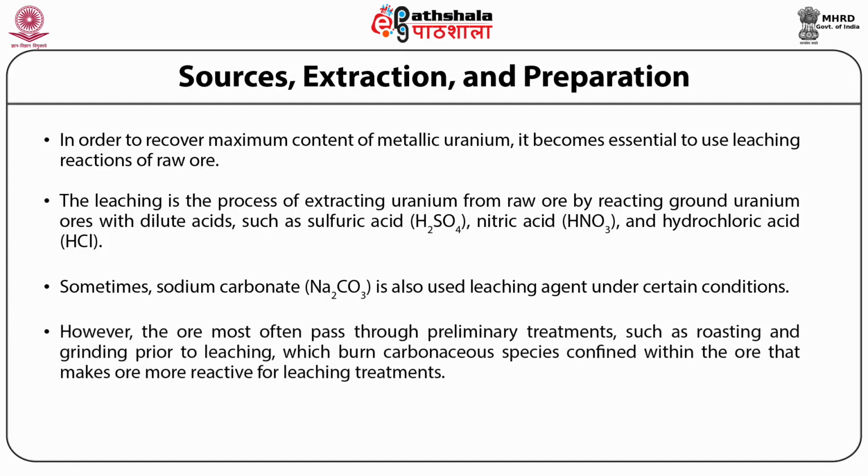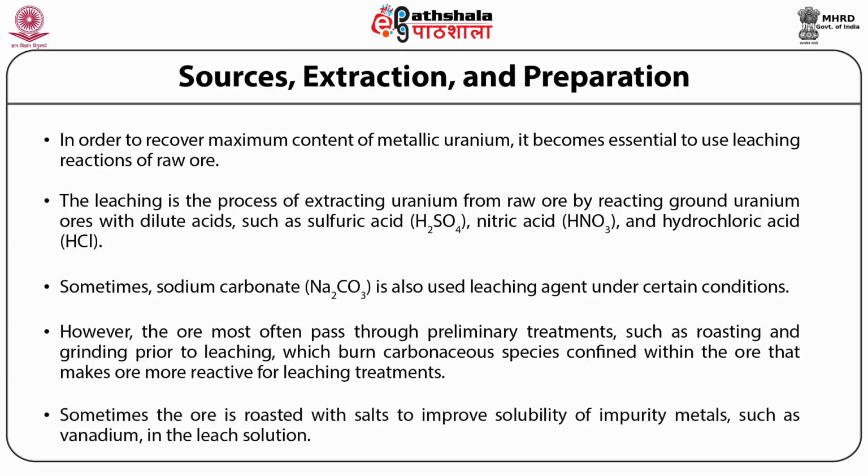However, the ore most often passes through preliminary treatments such as roasting and grinding prior to leaching, which burns carbonaceous species confined within the ore, making the ore more reactive for leaching treatments. Sometimes the ore is roasted with salts to improve the solubility of impurity metals such as vanadium in the leach solution.